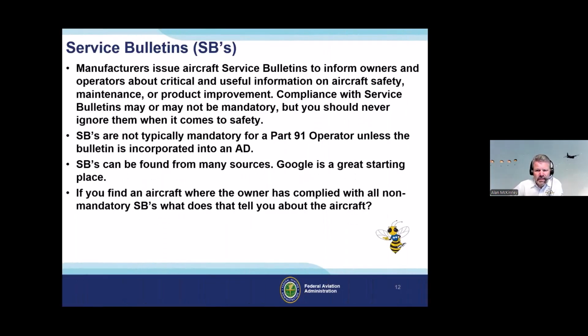Service bulletins. Are service bulletins important? Well, they are important because they're informing the owner operator that there's an issue that could be a safety issue that hasn't quite escalated to the level of an AD, but is a known safety concern. So are they mandatory? Well, the answer is it depends. They could be, and they may not be. Typically, service bulletins are not mandatory for Part 91 operators.